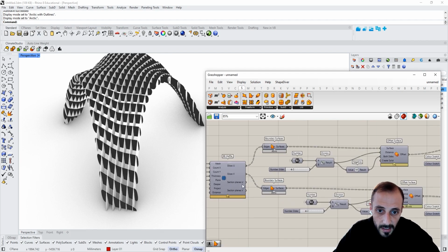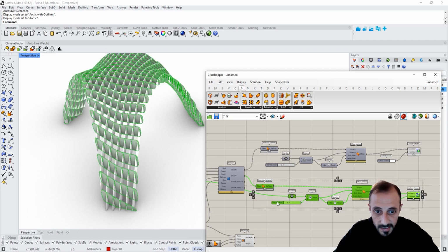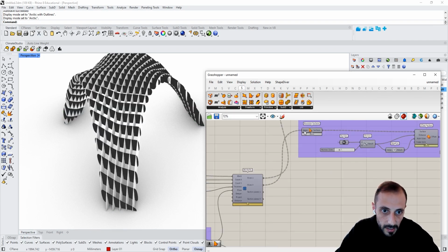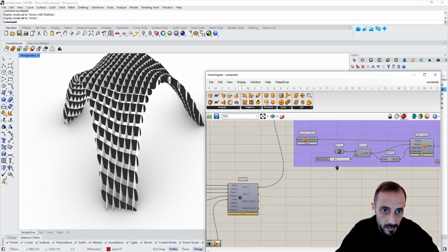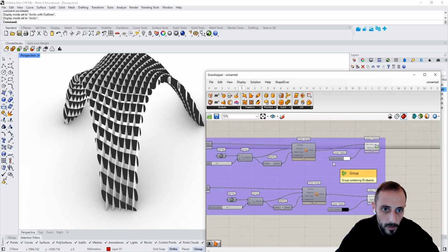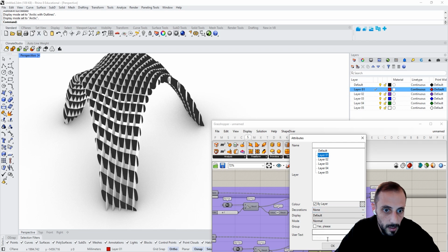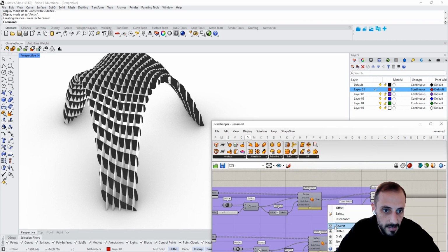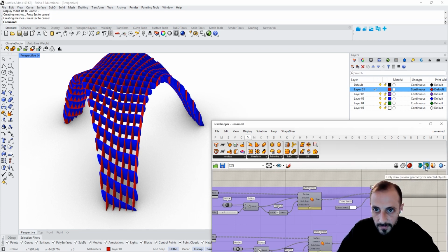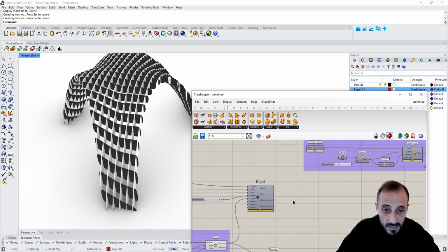But the other thing that I wanted to do is actually take all these pieces. This is 3D visualization, so I can maybe group this and put it upwards, and wire display hidden, wire display hidden. This is good, but it's mostly for 3D visualizations, and I can just bake this into layer 1 and bake these into layer 3. And if I turn everything off, we do have this. That's fine. And now we only have the visualization.